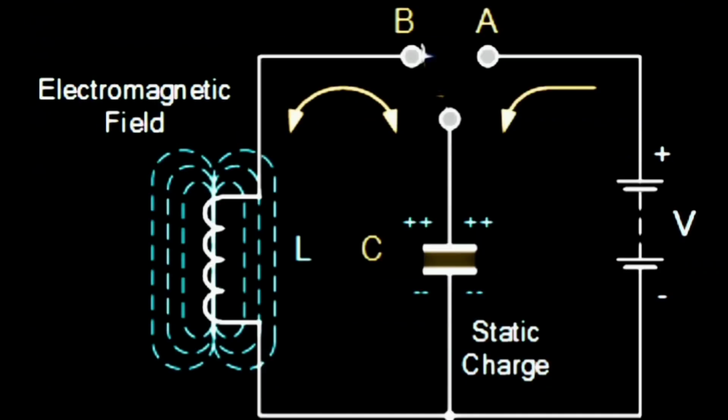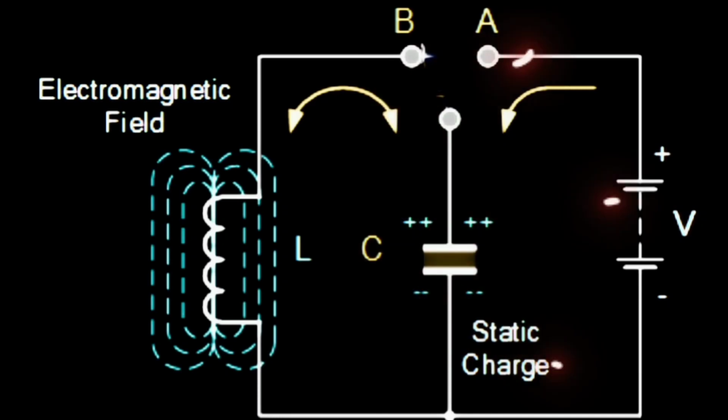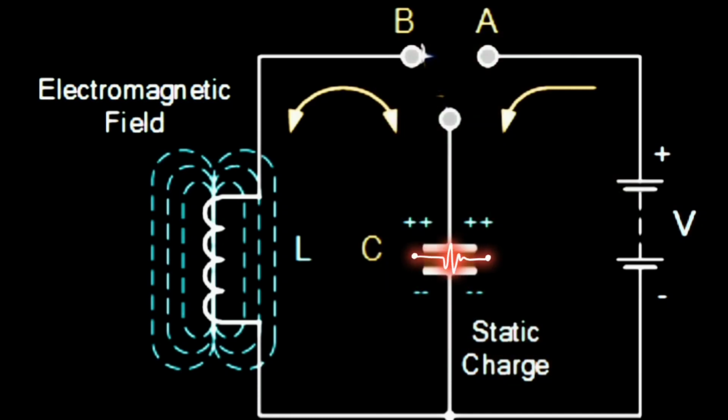an electrostatic field. During this transfer of energy from capacitor to inductor or from inductor to capacitor, there is an energy loss from the feedback resonator in the form of radiation, or dielectric loss, or heat dissipation from the inductor coil. If this loss is not compensated, then we won't get sustained oscillations at the output of the oscillator.